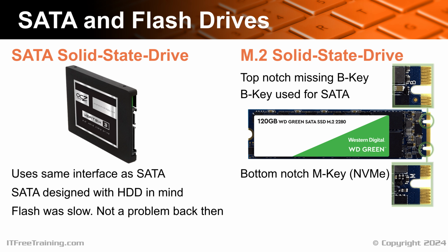Although this solid-state drive only supports SATA, it also has the M key notch, so it can also be used in M key slot motherboards. Some M.2 M key slots on a motherboard will support SATA and NVMe. In order to use SATA, it doesn't matter if the M key notch is present or not. However, not having this present would reduce the number of motherboards the storage could be used in, since the storage could not be used in M key slots that support SATA. Thus, all SATA M.2 storage devices that I have ever seen have the B and the M key notches.